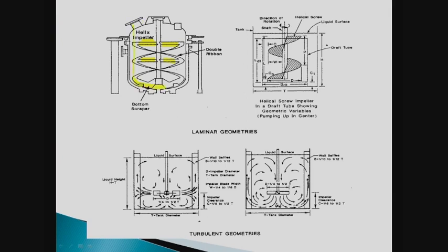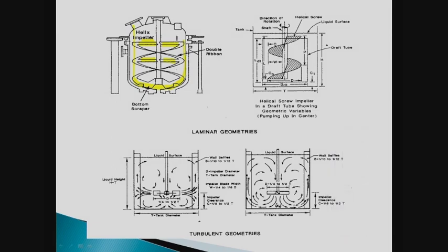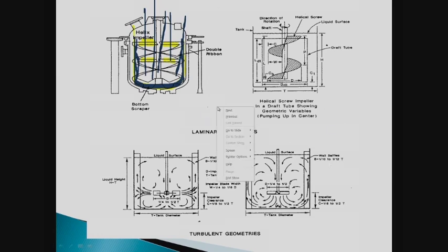So you have the anchor down here coming around and up. So if I was to redraw that, let's try color and let's try blue again. I would have the anchor come down here and support the helix, right? And I would get rid of these crossbars. The reason why you would want to get rid of the crossbars is so that you can come in from the head and make process measurements all you want to, without being affected by the rotation of the impeller.